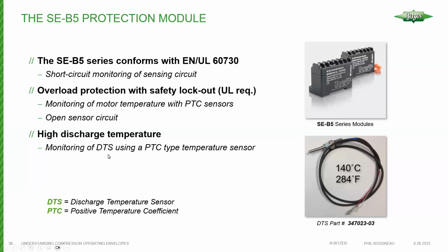So with the IQ module, the discharge temperature sensor is included by default on all packages. So if you're applying a compressor and you're not using the IQ module, for example, then I recommend using the high discharge temperature sensor whenever possible. Even if you don't have auxiliary cooling, it has benefits. Like I said, with unloading, but if you've got a compressor that's wearing over time, the discharge temperature sensor is going to give you more information about the operation of that compressor. And for the cost of a discharge sensor compared to a compressor, frankly, I think it's a good accessory to add.